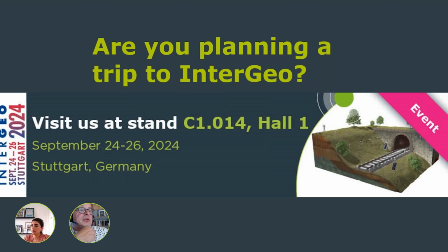Generally, at 30 minutes reporting rate, we assume 12 to 15 years of battery life, but the 2-second reporting rate is usually only done for very temporary observation. So let's say for a week or something like this, and then they switch back to a different reporting rate. So that doesn't strain the battery, but if it's permanently on this high reporting rate, it's of course reducing the battery life.